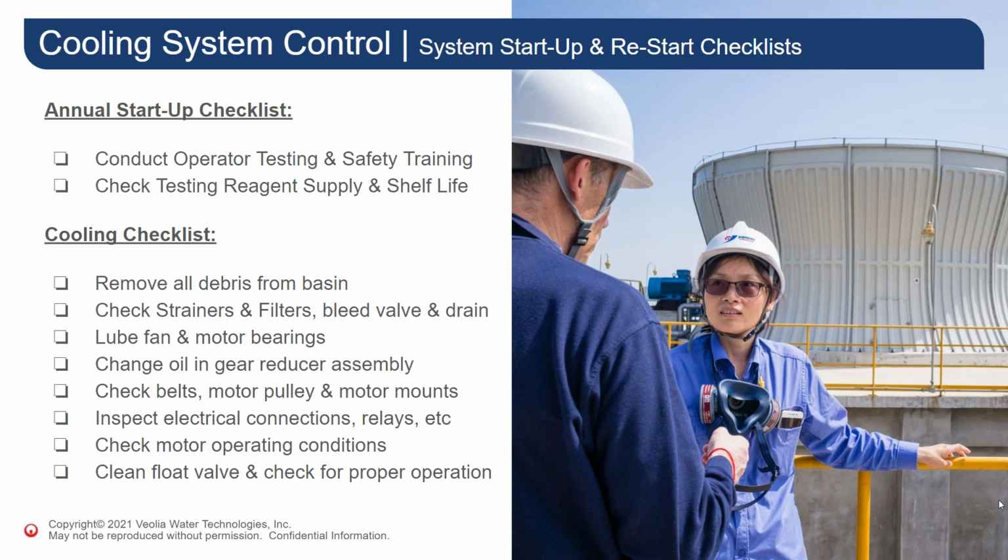Remember, our ultimate goal is to promote efficient heat transfer and water conservation throughout the upcoming cooling season by eliminating the water-related problems. Again, scaling is the formation of deposits due to supersaturation of any dissolved solids in the water. Scales are commonly calcium carbonate, calcium sulfate, calcium phosphate, and various forms or combinations of iron.